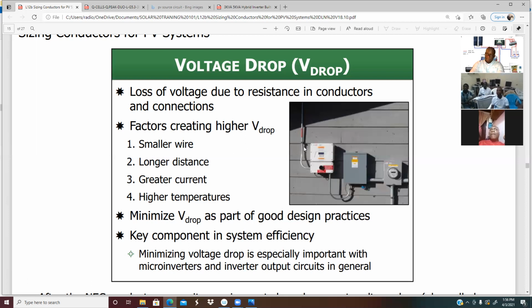But you have to be careful how you do your sizing. Instead of losing 45% or 50%, you should lose 5% of voltage drop, because losing 5% or 10% has no effect on your system. So you do your configuration well, and from there your wire sizing calculation.